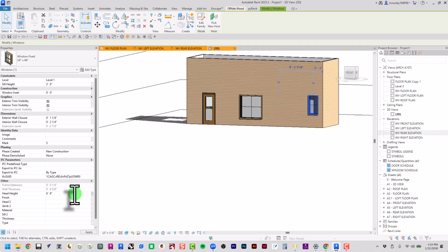When our contractors are looking at the plans, they're cutting every stud to be exactly 8 feet, and then they're cutting all of their supporting studs to host the header that supports the door or the window that's hung from it. And if they can already understand that all the openings have a head height of 6 foot 8 inches, then they can calculate how many openings there are, multiply that, and figure out how many to cut.